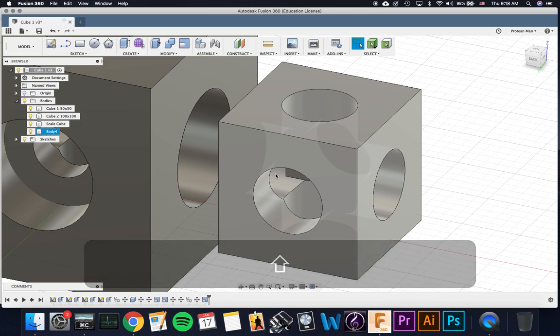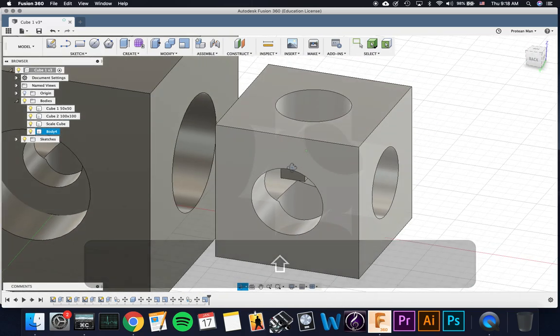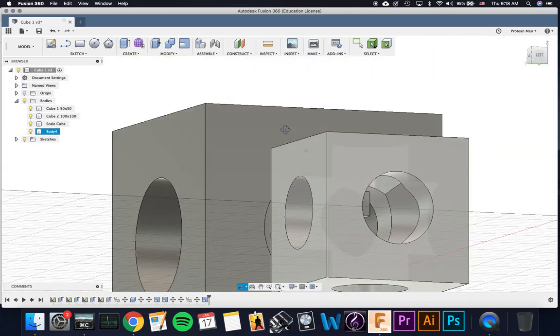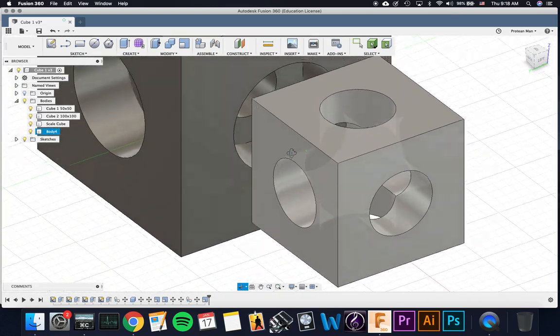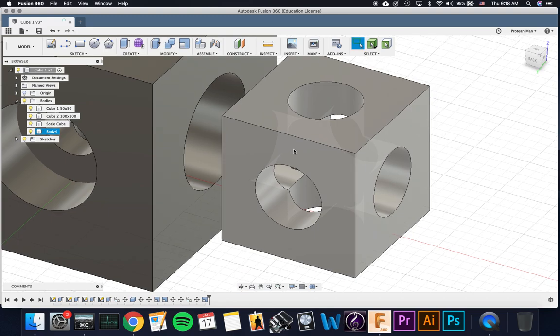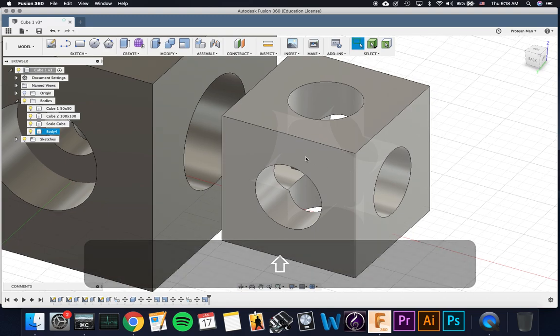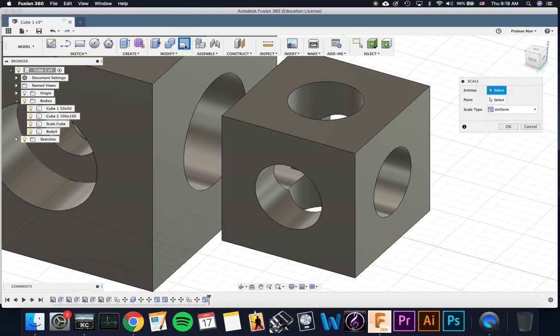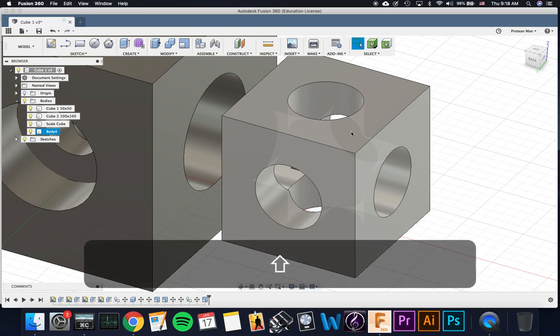So what I did before when I moved the camera that I didn't mention is when I hold Shift and move the middle mouse button, you notice how it rotates the whole camera. We've done this many times already. But if I hold Shift and click the middle mouse button, it added a green dot. Again, you can see where I click. I don't hold down that button, I just click once. That green dot is the camera rotational point. The same idea as our scaling point, putting it at the center. Now the camera rotates around that green dot.